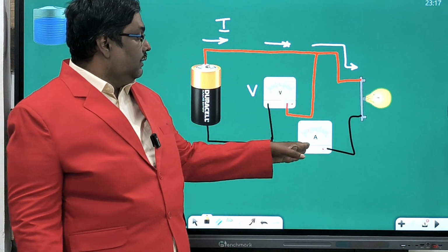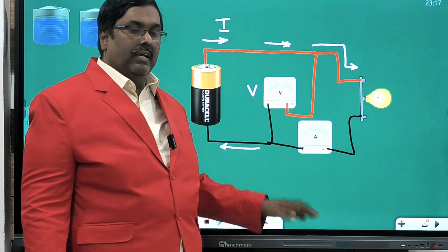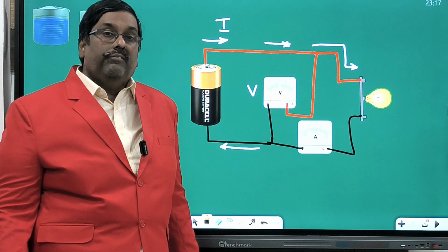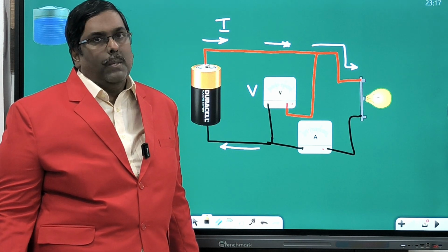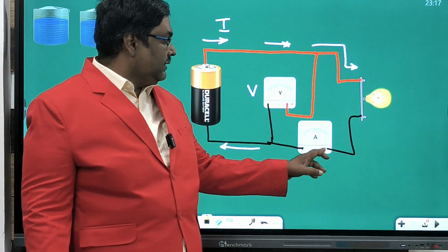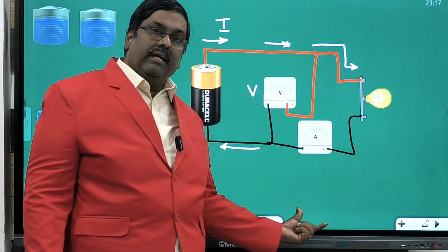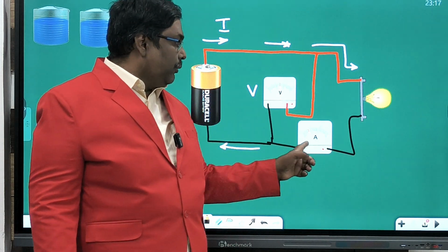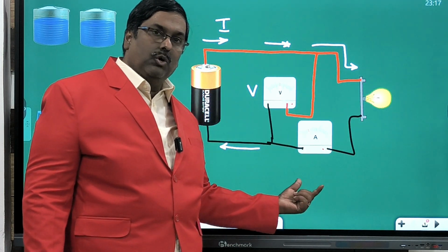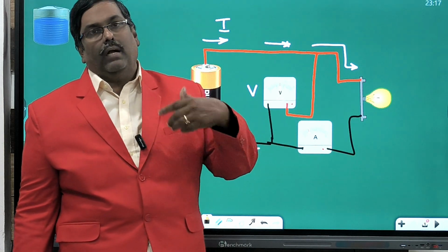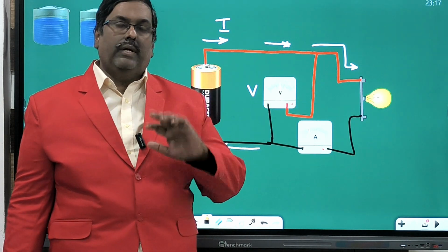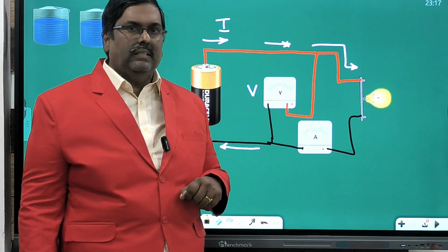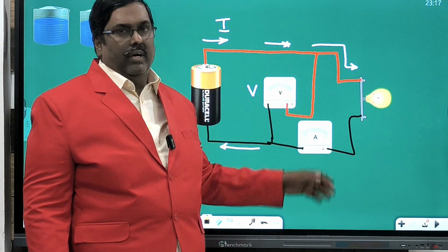But in a panel, if they are fitted like this, you should know what an ammeter is, and if you don't have an ammeter, how to use it. In some circuits, they give a resistance and take two wires in parallel to a controller. That means they put in the resistance and measure the voltage drop, and according to the voltage drop the controller will act. We give the voltage drop to the controller, which is in millivolts. The controller senses the millivoltage and acts like a regulator.